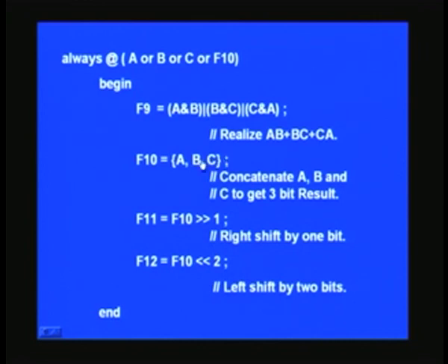Suppose in addition to this you want to add 3 zeros at the LSB. All you have to do is put a comma here and then say 3'b000, or any other data you want. If you put 111, 111 will be concatenated towards the LSB side, right. And so is the case, you can insert anywhere, or instead you can put any other signals which are already available here.